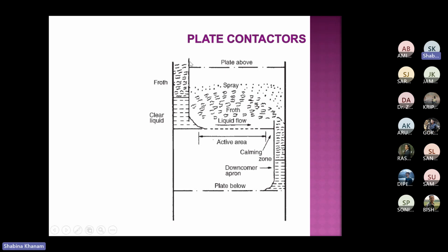When I'm considering this downcomer, the liquid and the froth are coming together to the downcomer, and liquid is not allowed to separate. Then the froth will come with this liquid over the plate. So that is obviously an undesirable condition. Vapor should move up, not down with the liquid. So we consider that downcomer backup should be checked.